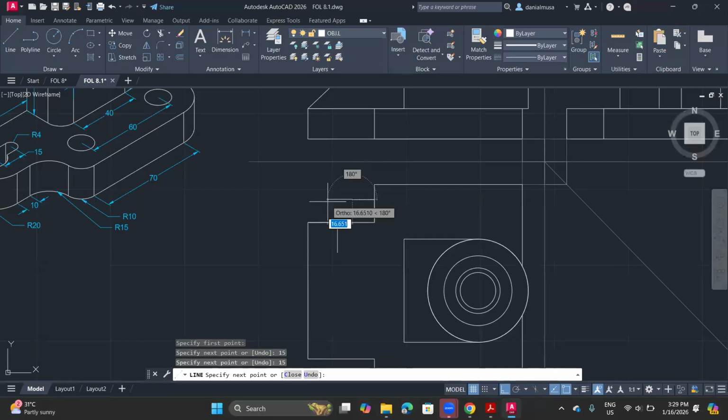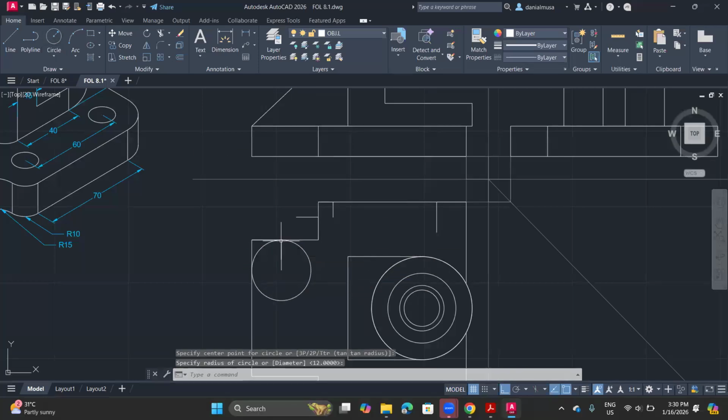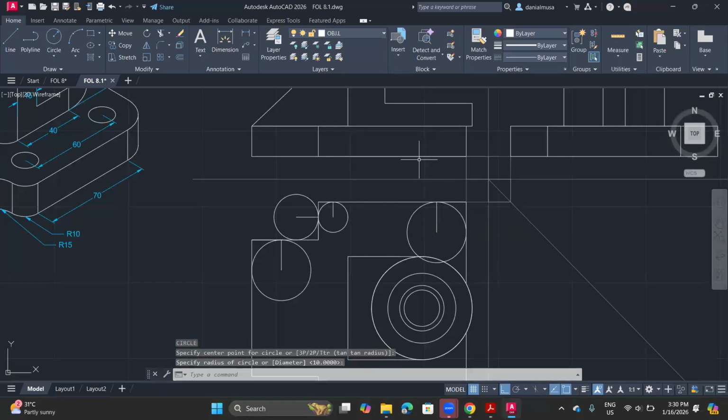And outside. And here is the blue. We draw at this side first. And here is two blue. And we draw a circle. Because we already inserted the radius, so we just use the circle to connect it. Just enter to repeat the tool. Enter again, repeat it. Okay, after that, here we just use the trim to remove the outline that we don't want.